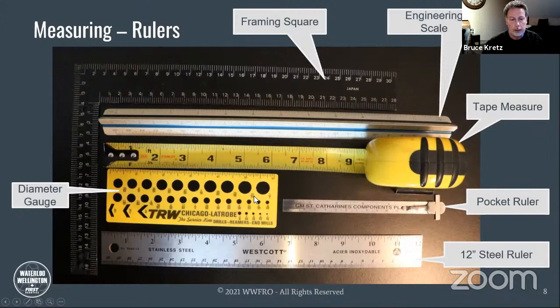And it will be used to either draw a circle with a pencil, or if you have a drill and you don't know what size it is, you can slide it through the appropriate hole and it will tell you how big the drill is. It also has some chevrons here, and I will talk about that a little bit later. That is drill angles, included drill angles.